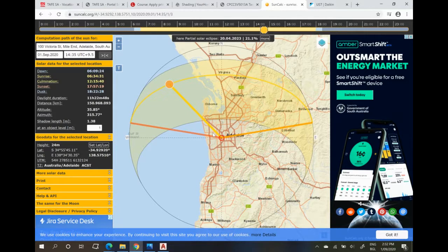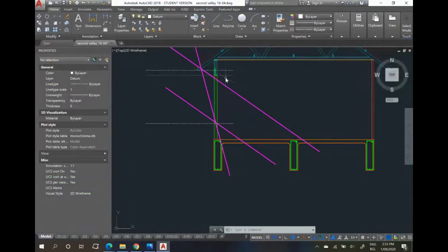That's where programs like Revit are super handy, in that they can map that sun throughout the day, and you can place that building in context with other shading devices and things like that, and get all of your shadows happening to get a real true and accurate reflection. But for the simple calculations for understanding that concept, this type of approach is fine. So that's the concept behind determining adequate eaves width and resultant solar penetration in wintertime.